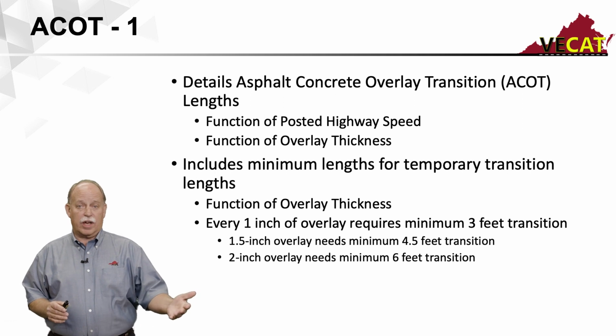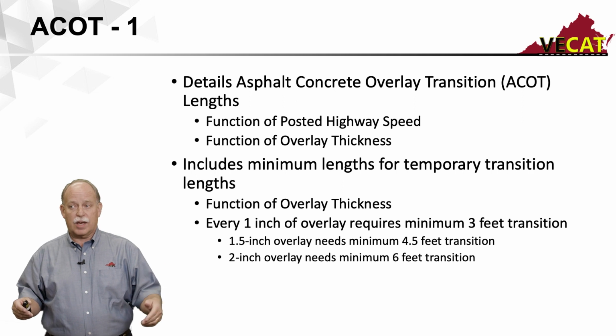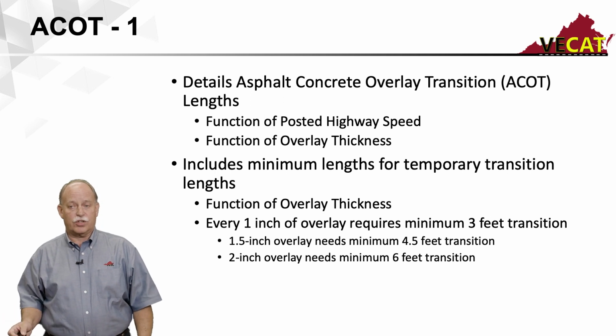If you've got a 2-inch overlay, it's the same thing. It requires 3 feet for every inch, so 2 times 3 gives you 6. So in this case, for a 2-inch overlay, you need a minimum of a 6-foot transition.